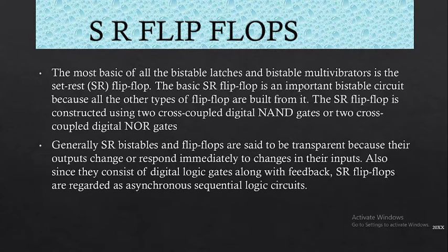Generally, SR bistables and flip-flops are said to be transparent because their outputs change or respond immediately to changes in their inputs. Also, since they consist of digital logic gates along with feedback, SR flip-flops are regarded as asynchronous sequential logic circuits. So, a flip-flop has two inputs R and S and also two outputs Q and Q bar.